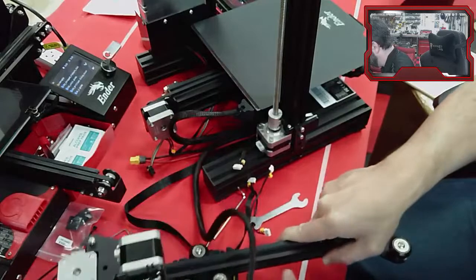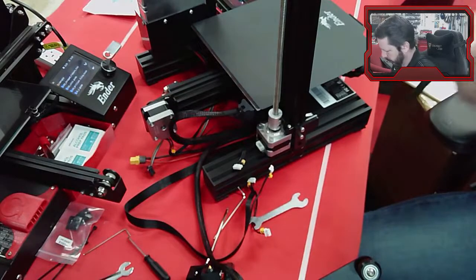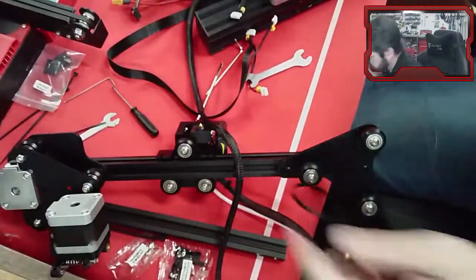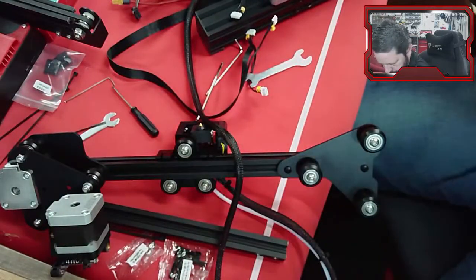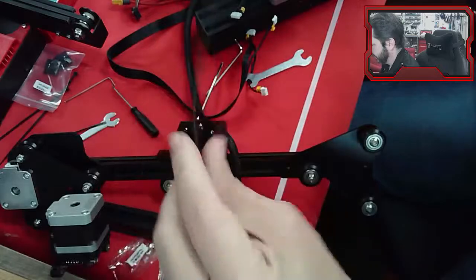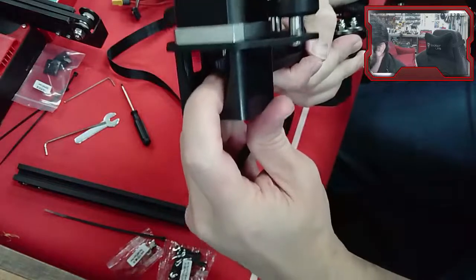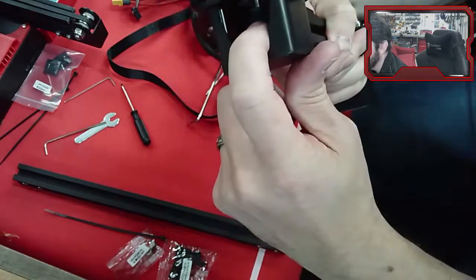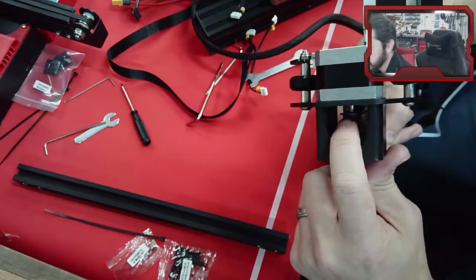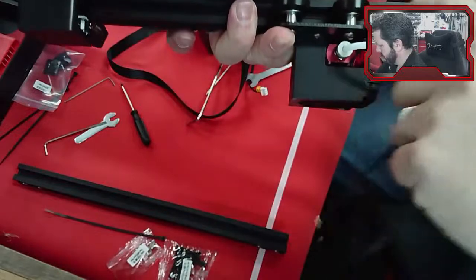Now, we need to get our belt routed. So the belt, these little gold pieces are going to fit in these little slots right here. The belt obviously has a side with teeth and a flat side. The side with teeth, you can tell where it goes in here. It has to go around. That's kind of hard to see. There's no light down in there, but this pulley has those matching teeth on it, so it has to go around that. And then it's going to run through this little channel and come back around.